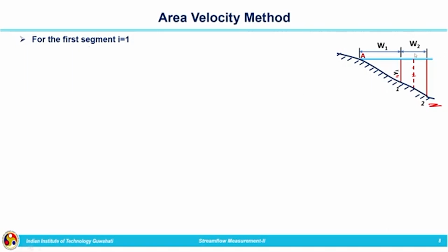We name different points A, B, C, D, and we need to get the value corresponding to CD, marked as x. Now, consider triangle AB1 and triangle ACD. These two triangles can be considered similar triangles, and based on the known values of width and depth, we can compute the depth at the midsection corresponding to segment 1.